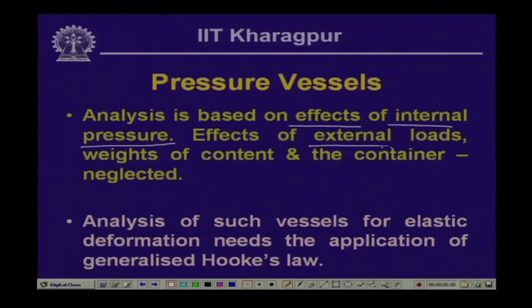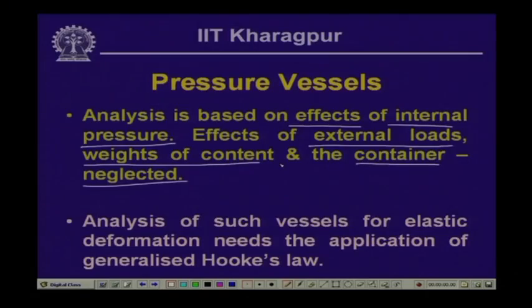But we neglect other effects, such as the effects of external loads, the weight of the content and the weight of the container. These aspects are neglected in this analysis. So, when we analyze these kinds of pressure vessels, we analyze the container for stresses only because of the pressure exerted by the content from inside. We do not take the weight of the content, we neglect the weight of the container, and we do not take the effect of any external loads acting on that particular container.